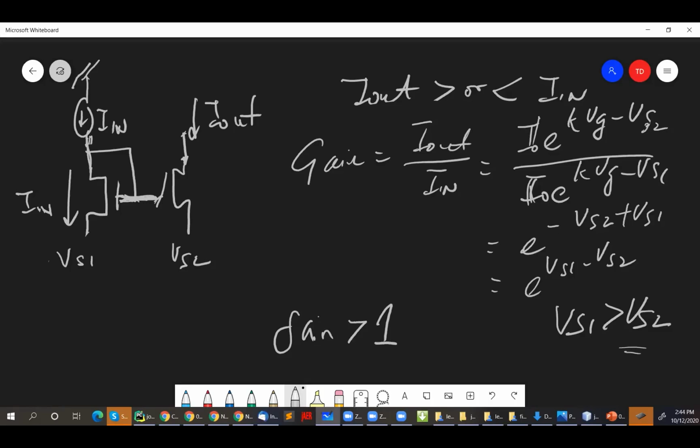Right, exactly, Nicola. So that means we don't want that case, because you don't want to have negative voltages, right? Because your power supply is from ground to VDD. It's all positive. If you want to make a negative voltage, it's possible, but it's messy. So that means you really want to tie this to ground, right? And then you would set this to a voltage that's greater than 0. Yeah, okay. All right, that's good, guys.